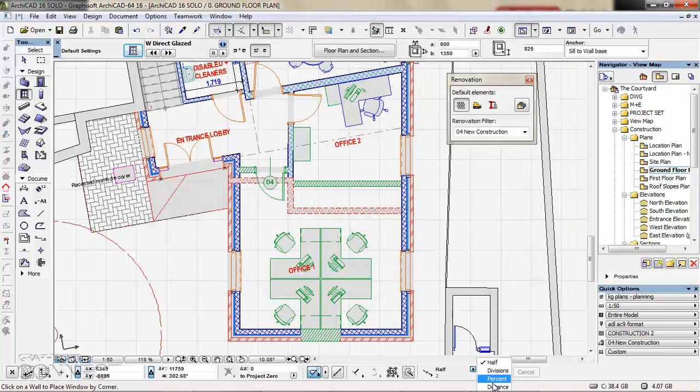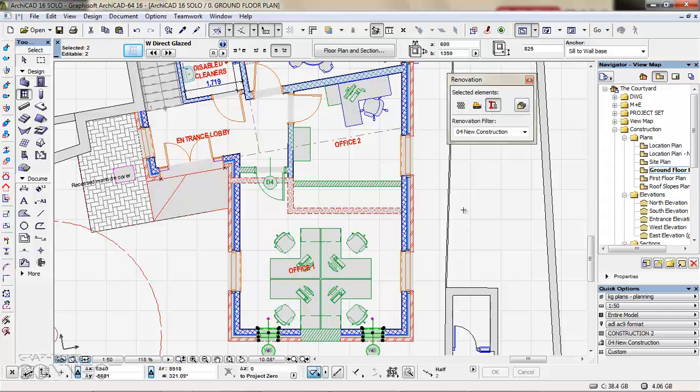I'll switch on my special snaps. That enables me to snap and count out the number of bricks so that I know when I place this window it goes into real brick sizes. I've mirrored a copy, and I'll also set these to new status. So we can see again these highlight in different colours, etc.